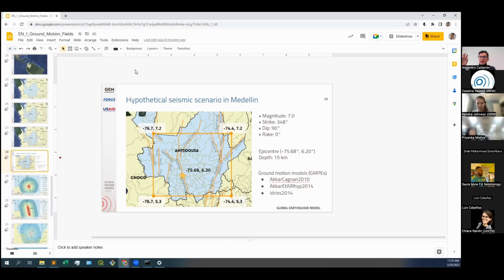Usually we detonate a small seismic charge or something like that, that will generate waves, and then those waves are captured by the microphones. The speed of those waves, how fast they travel, is a measurement of how stiff the soil is. And with that stiffness, we can understand if the ground shaking intensity will be amplified or not.